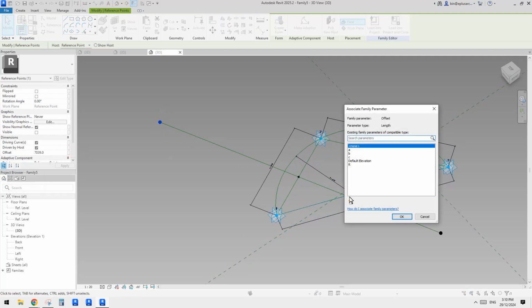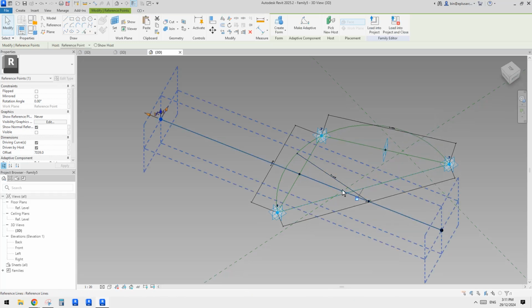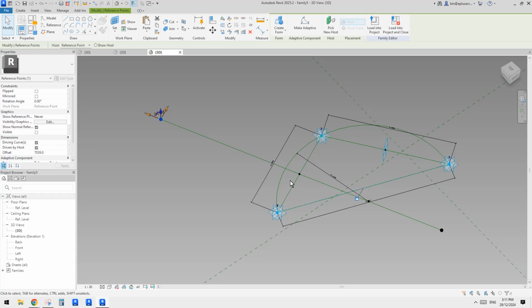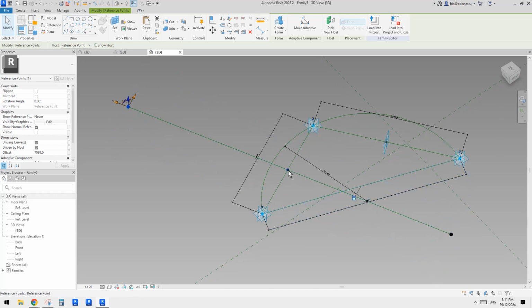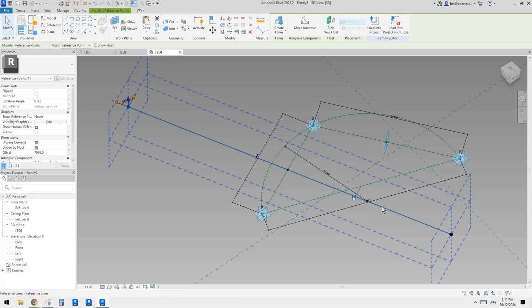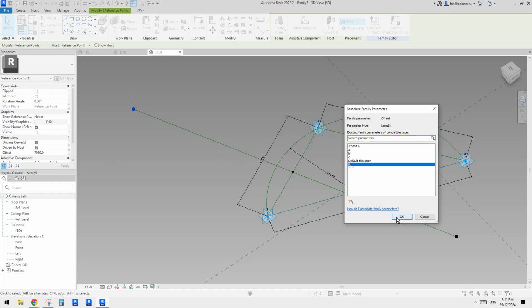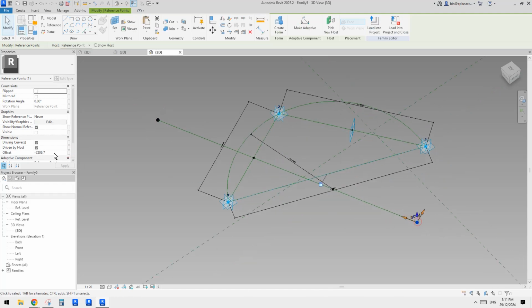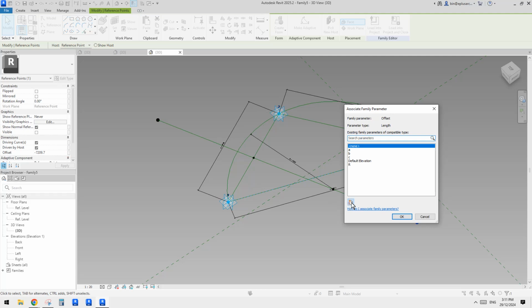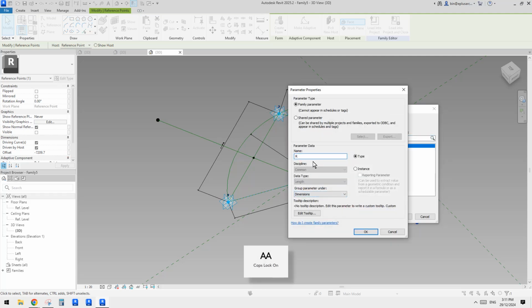So what we're going to do is just set this one offset. I'll create an offset, and then actually I'll use R, because see here, the distance between this point and this point should always be smaller than the R, the radius. So if I use the radius R, it will always be further than the center point. So I'm going to use R for this one, and then of course this one will be a negative R. So I'll create maybe R negative.